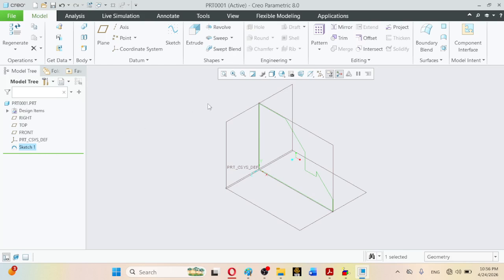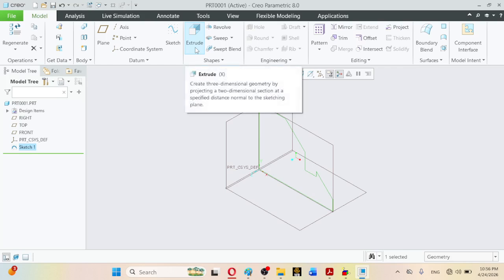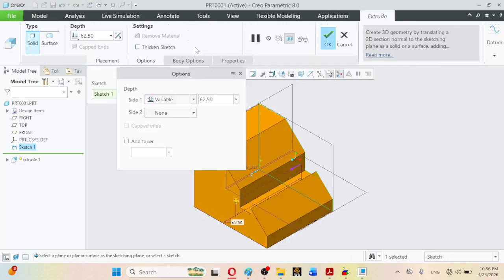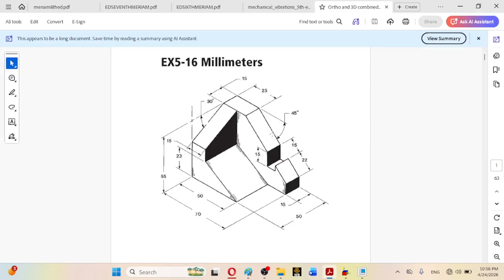And remember, once we click on OK, this sketch is selected, as you can observe it here. This is in green color. So if you do not click on the empty screen and you launch the extrude command, it will be instantly extruded like this. So for this base face, it doesn't matter whether it is extruded in this direction or in the other direction.